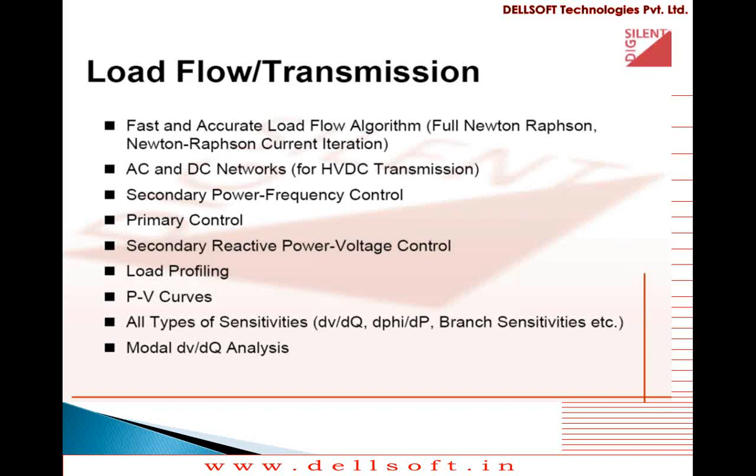Also, we can profile our loads over different periods of time. We can also generate PV curves based upon our load flow analysis. All types of sensitivity based on dV/dQ and branch sensitivity tests we can conduct. Modal analysis based upon dV/dQ can also be done. So load flow transmission has these features included in this software, and a lot more, which I will show you when we do the analysis on the software.